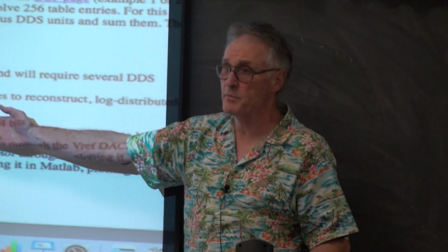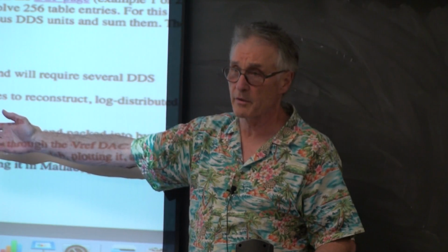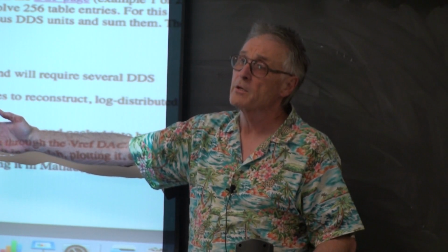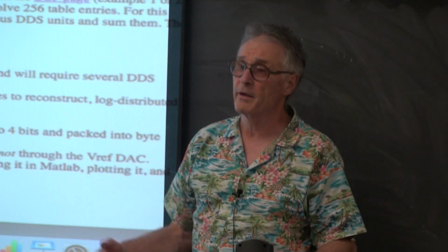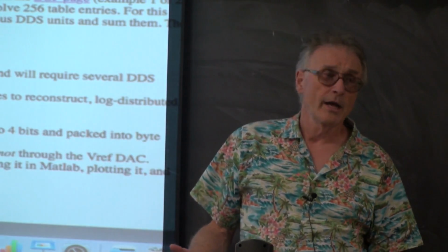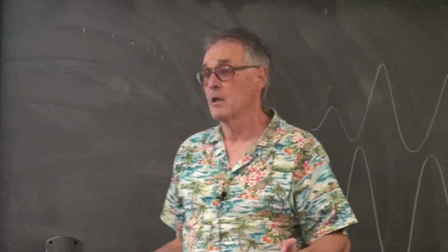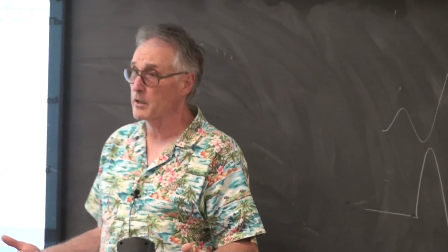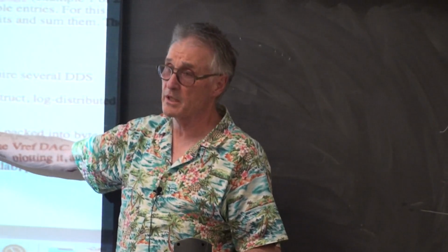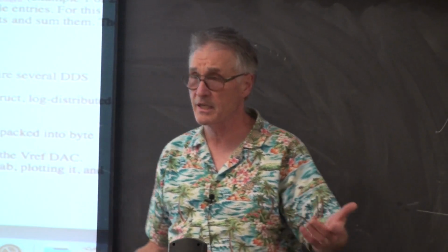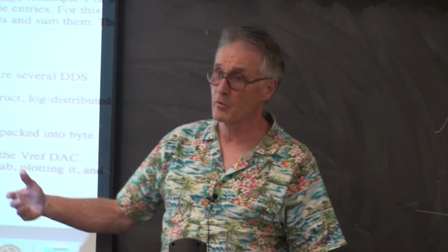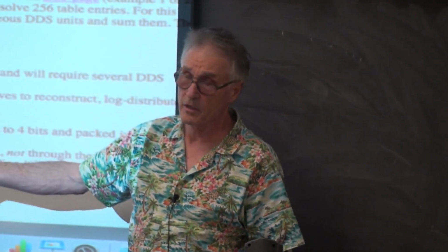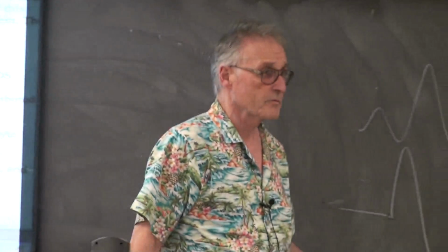So the sampling frequency required in the DTMF dialer is going to inform what you have to do for the speech, because you're probably going to put everything into one interrupt service routine. So if you come up with a required rate of 8 kilohertz for the DTMF dialer, you're going to want to use the same frequency for the voice. If you come up with 16 for the DTMF dialer, you're going to want to use 16 for the voice, so that you can put it all in one interrupt service routine.